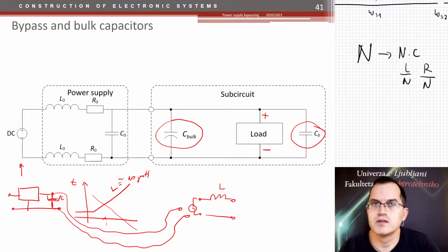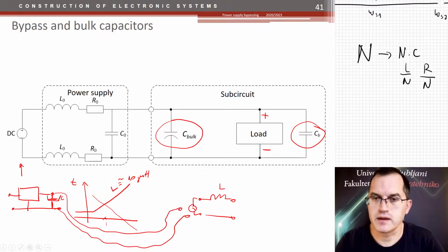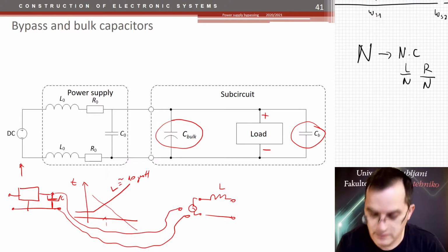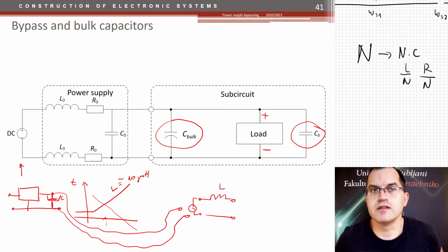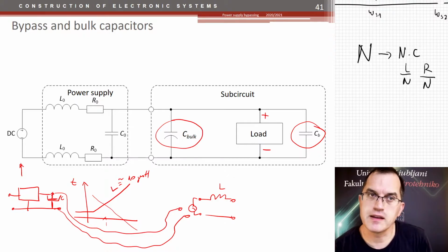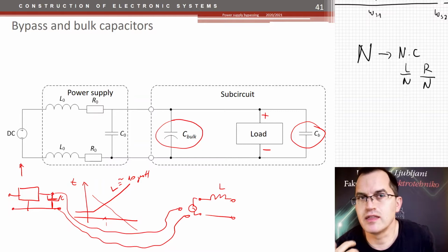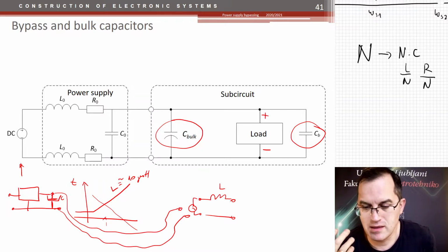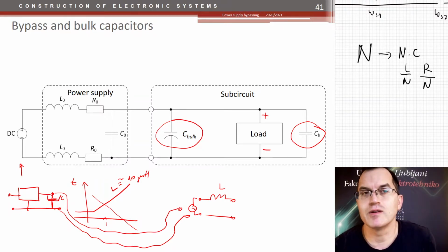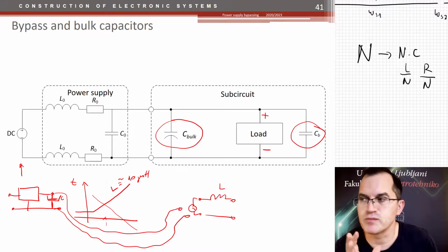So to finish, I can say the following. The choosing of bypass capacitors is essential for your circuit, even to operate properly. And the next thing, the value of these capacitors and how you place it would then not just enable your circuit to work, it will also minimize the noise spread through these power supply lines, power supply tracks over the whole PCB.